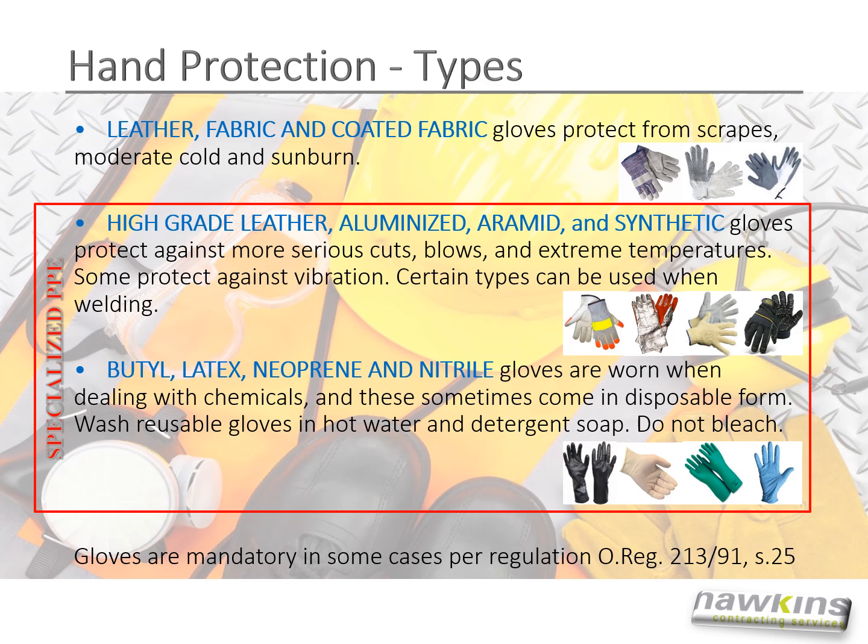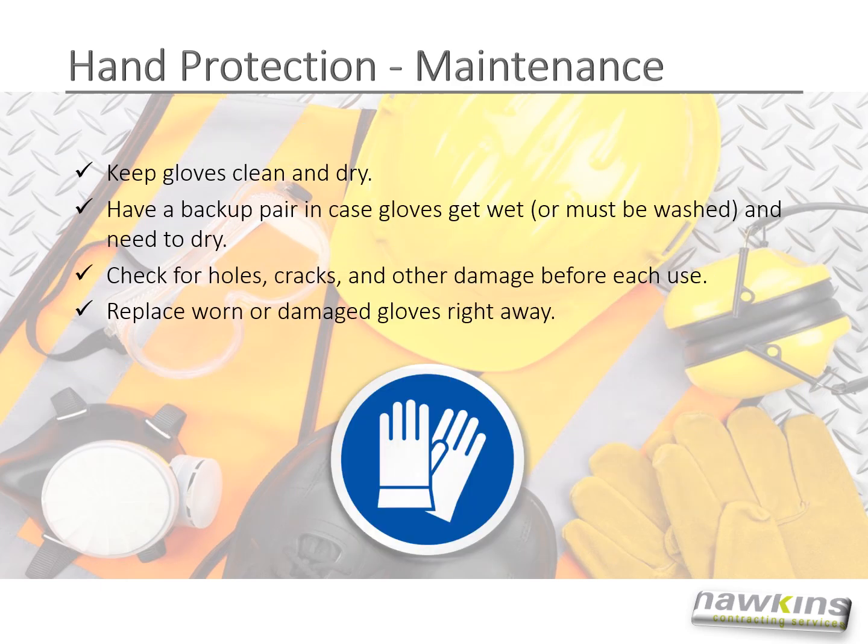Do not bleach them. Gloves are mandatory in some cases per the construction regulations for Ontario. Careful not to neglect your gloves. They too require maintenance. Keep gloves clean and dry. Have a backup pair in case gloves get wet or must be washed and need to dry. Check for holes, cracks, and other damage before each use, and replace worn or damaged gloves right away.